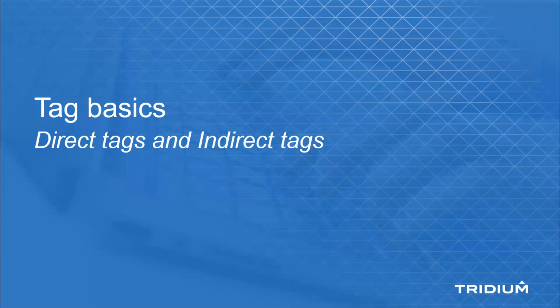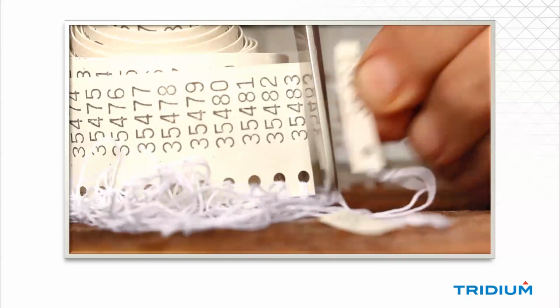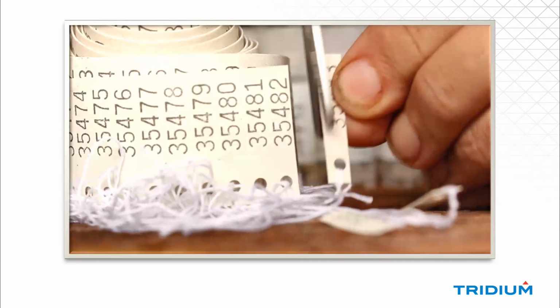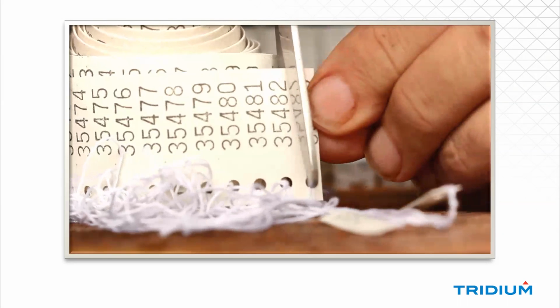So, tagging basics. There's a direct tag. I can go and pick a point here and then I can apply these tags, and these are direct. I'm just typing them from the Haystack. So I put HS sensor, and then there's another direct tag. But I had to physically go to that point and tag it. And that can be tedious, right? That's essentially going to every point and then trying to put the context in of where it's at. So I know none of you want to do this. And anytime I talk about tagging, this is what people think you have to do.